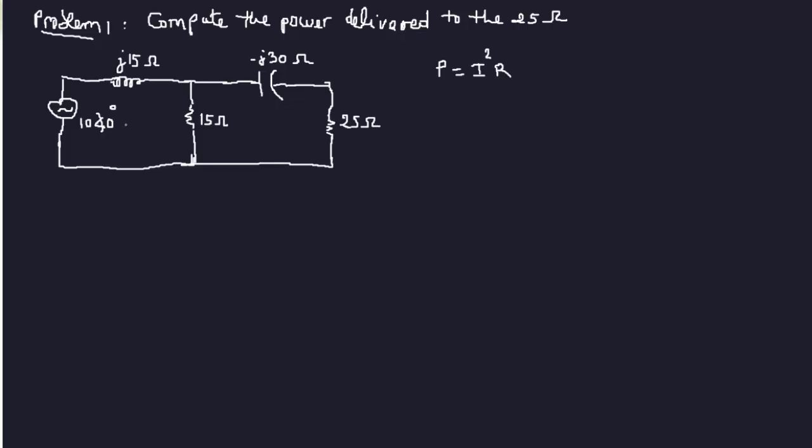Okay, so I'm going to go ahead and assign my signs. Here's plus minus here. I can put plus minus here, plus minus, and plus minus, just to keep it easy. And I'm going to assume that there's a current here, I1, through that first loop, and then I2, second loop. For the signs, you can actually choose your own, and we're still going to end up with the same answers. But just make sure you are following the standards.